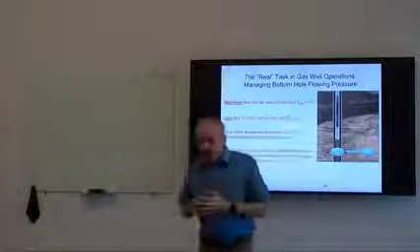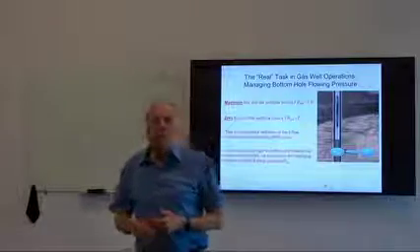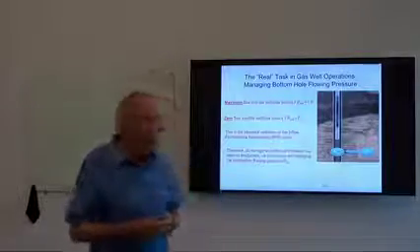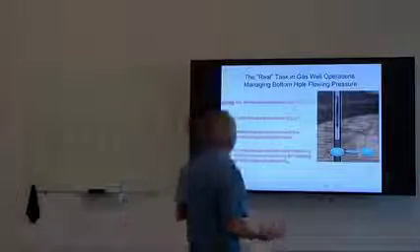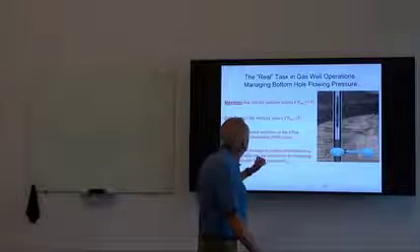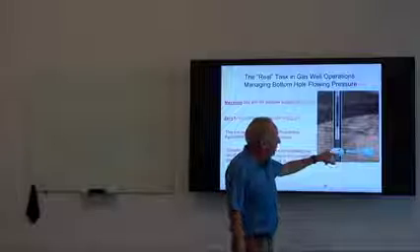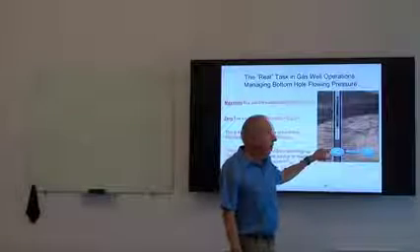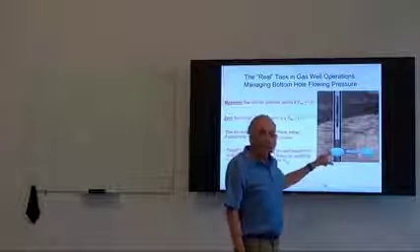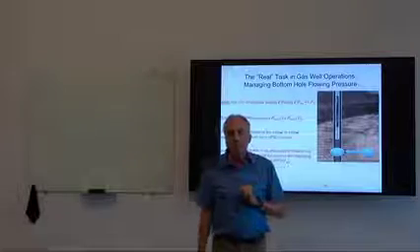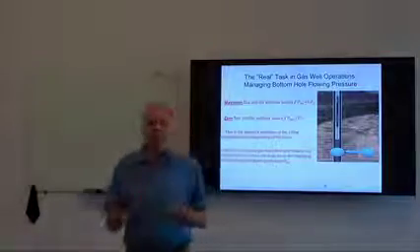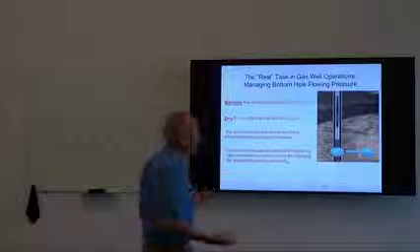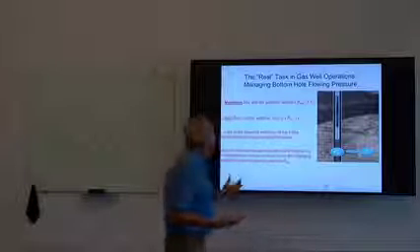And we could speak about a theoretical open hole flow, which is the condition where it would be if we reduced this pressure inside to zero. We would have absolute maximum flow. If we had zero pressure bottom hole, then we have the maximum pressure difference across the perforations.